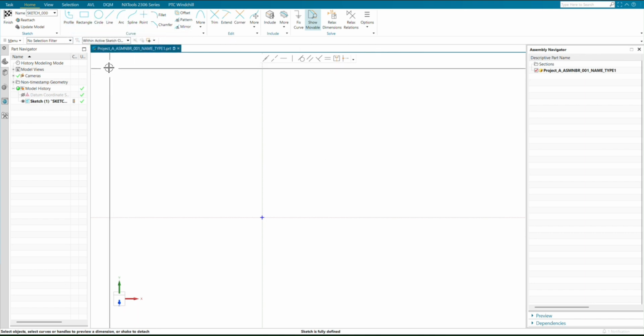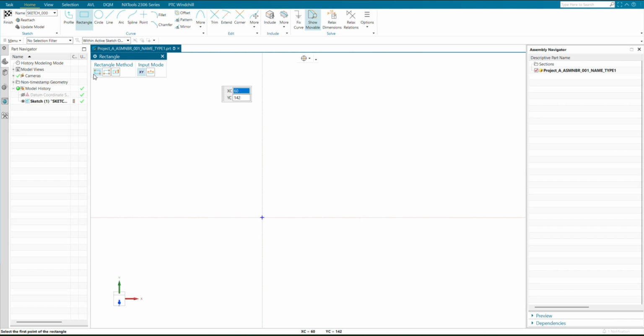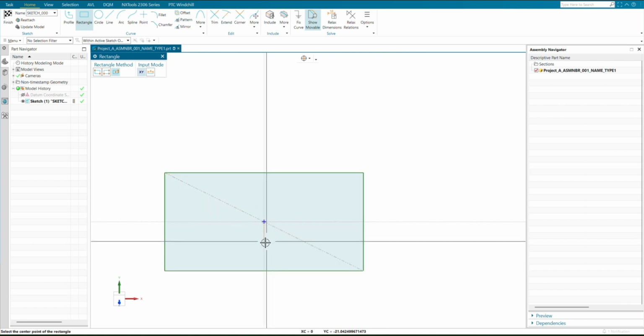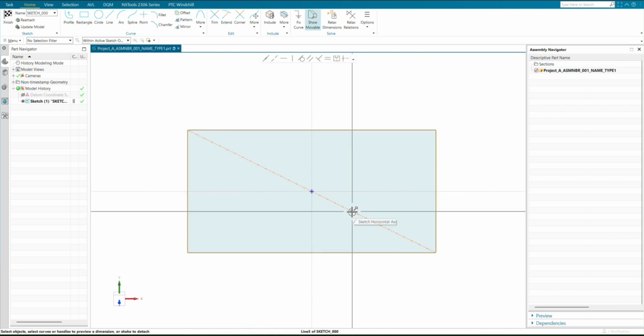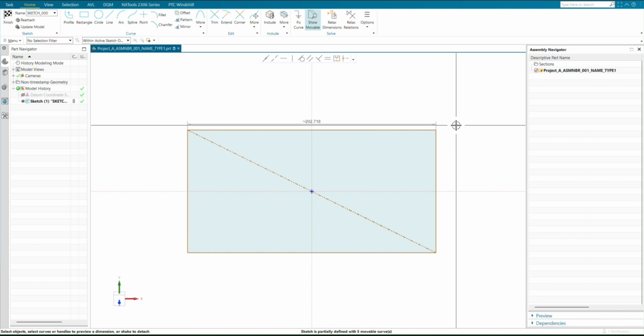There is an important rule in CAD. A sketch must always be fully constrained. If a sketch is not constrained, it may move accidentally. This can create problems when modifying the model later. To constrain the sketch, apply horizontal and vertical dimensions relative to the default reference axis. If you want faster dimensioning, you can enable rapid dimension from the customization options.